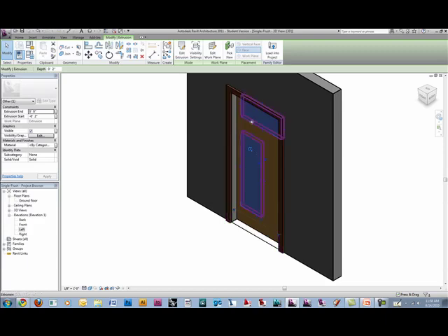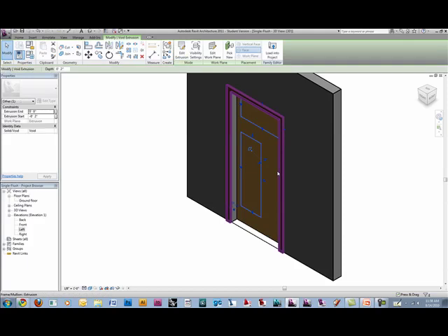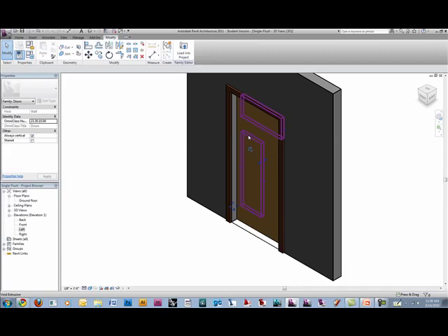So to do that, it's really easy. You click the geometry you made, you come over here where it says solid void, drop it down to a void. The reason I didn't draw it as a void first is because if you're drawing it as a void, it automatically cuts it as soon as you say okay, so you may cut stuff that you didn't want to cut. It's easier to do the solid and then tell it to cut. And it's also hard to see the void when you get done with it. It disappears and just cuts stuff, and you're like, well, where's the void? So if you didn't draw it in like the perfect spot, you'll never be able to find it again. So like these are easier to find.